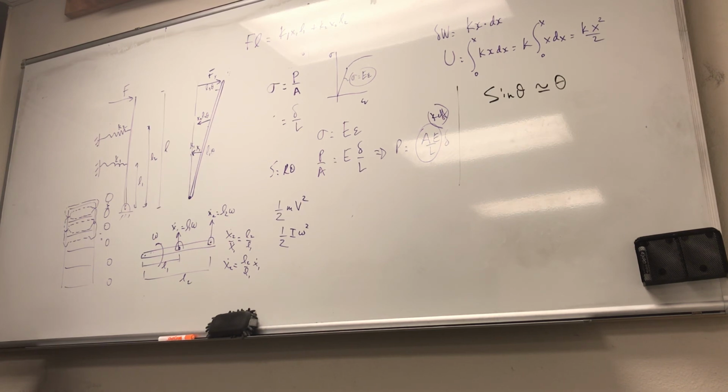In fact, that's what it says here, viscous damping is the most commonly used damping mechanism in vibration analysis, right? It's air dampers or fluid dampers. When mechanical systems vibrate in a fluid medium, the resistance offered by the fluid to the moving body causes energy to be dissipated. In viscous damping, the damping force is proportional to the velocity of the vibrating body, as opposed to Coulomb damping or the rest. Now, what are the typical examples of viscous damping? Well, you can probably have two surfaces where you have a film, fluid film in between.